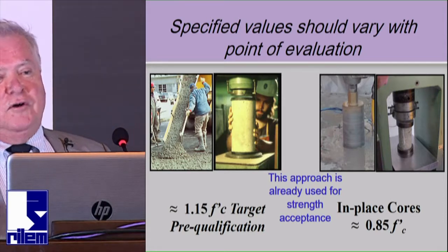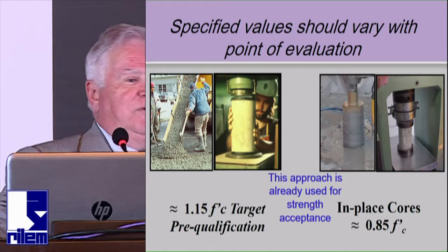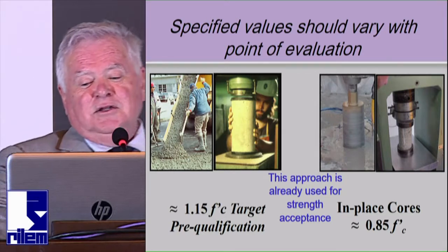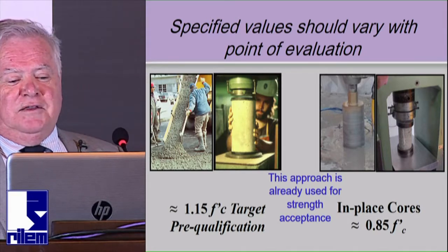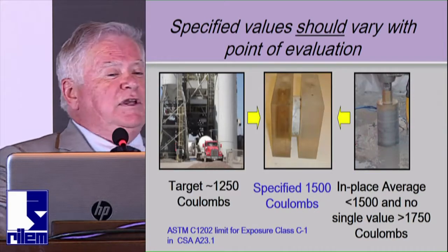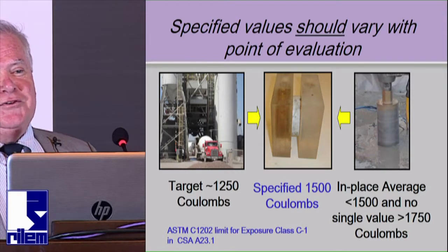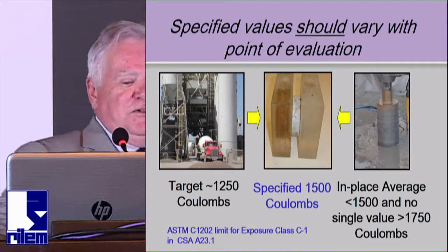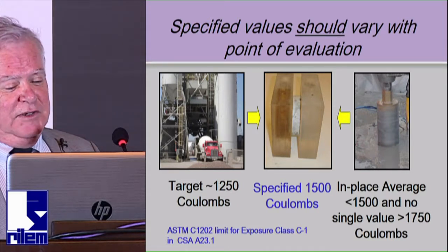If one cylinder or cube is tested low, there's statistical evaluation of cores based on running averages, and you would accept concrete on occasion that's less than the specified strength, because you know that some of that is due to the variability of the test method. And we do that in our Canadian spec for air content and air void spacing, but not so much interest in India because you don't have the freezing issues we do in Canada. But we do that for the rapid chloride permeability specification.